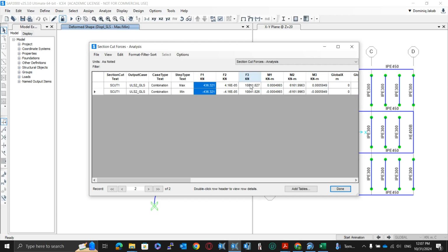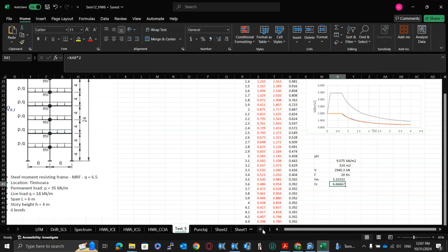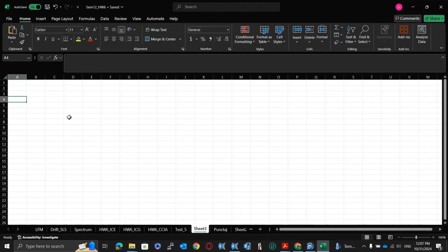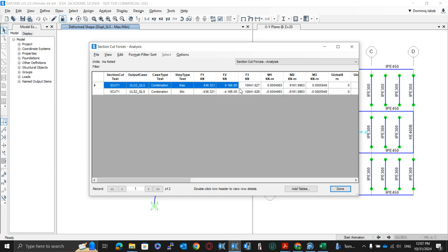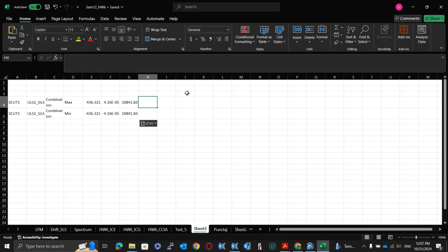You take that, you go in an Excel and you define something like this for all 5, okay? You take this as absolute value and this an absolute value. You have the relative displacement from displacement for ultimate limit state combination. You put the ratio and you get theta on X and on Y.